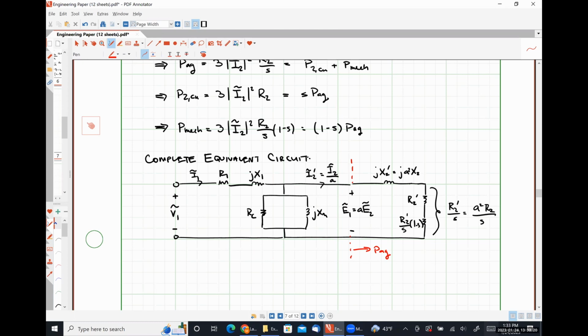Technically this doesn't work for a squirrel cage system, but we can have an effective turns ratio, which the overwhelming majority of the time is 1. So it makes life easy. We don't have to do anything to refer stuff from the rotor side to the stator side.